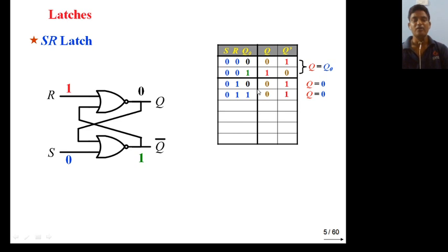Next, now for 1 0, this is your 1 0. Okay, in 1 0 suppose the value of q is 0 0. Similarly determine this and this output. Now I will apply the shortcut method. S equal to 1, R equal to 0. First determine this. If S equal to 1, irrespective of this value, you can determine the value of this.